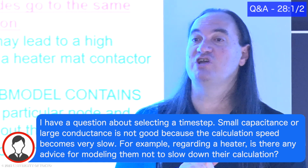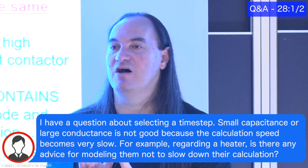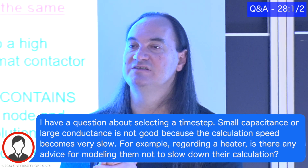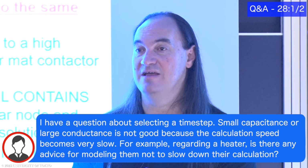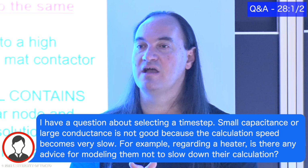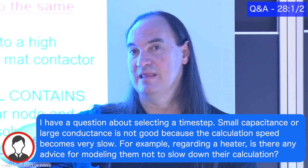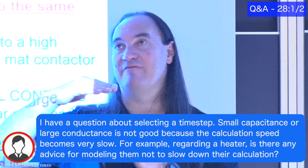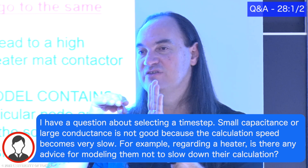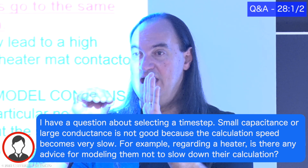One of the challenges we've had on the Roman Space Telescope is we have 150, 200 PID controllers. And there's just no good steady state emulation for that. So what I developed, and there's a paper in ISIS, if you're interested, I can send you the link, was basically something that did something very similar to that. It said, let me get an average temperature or an average power, and then once I've held at that average power for 10 iterations, let me see whether I'm at the temperature range I want to be. If I'm a little bit too cold, increase it slightly.